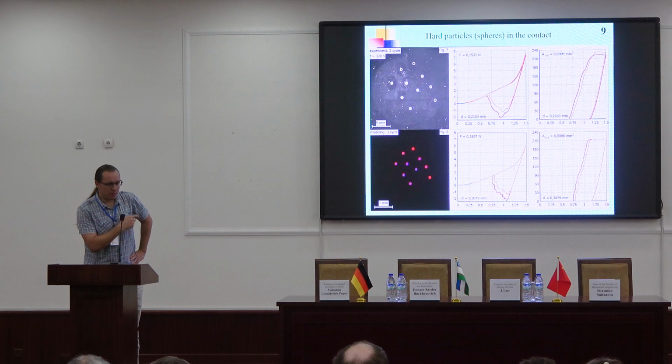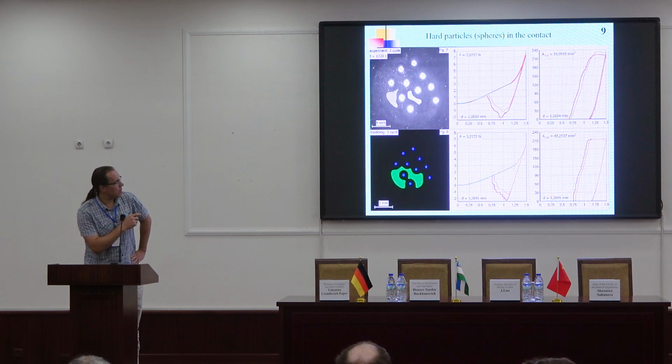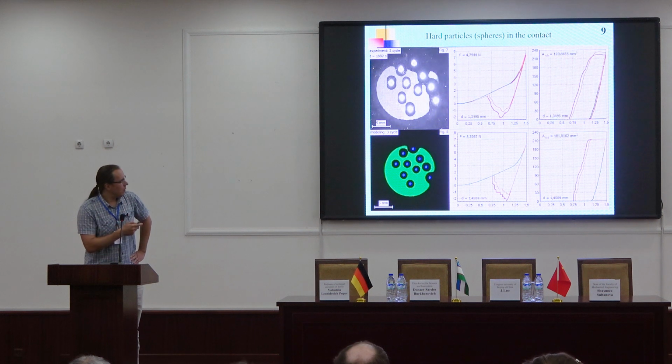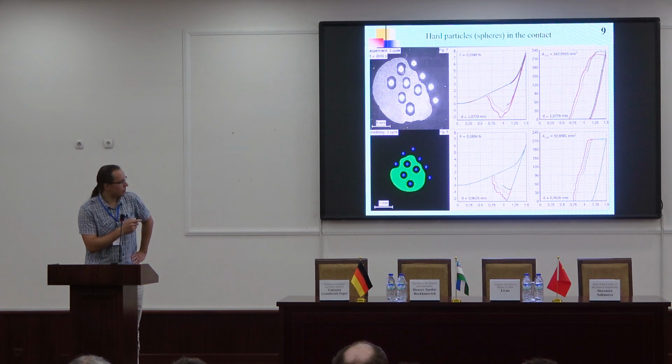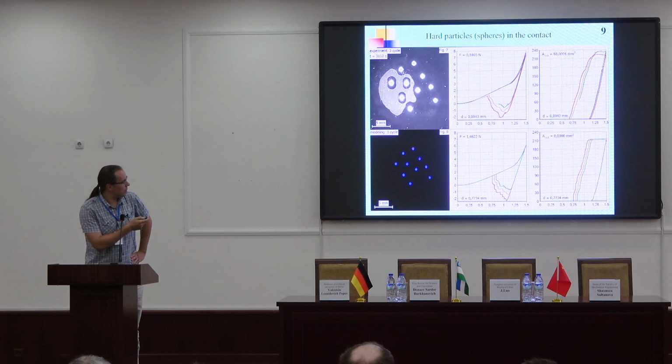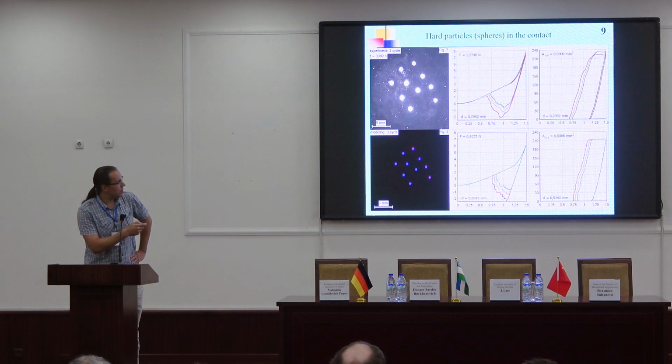It's a constant stiffness, and then after the appearance of the first direct contact between rubber and elastomer, we have observed also a non-linear dependence and then also a linear dependence. So we got different contact properties at different stages, different contact stiffnesses. There are also several indentation depths and several indentation cycles in simulation.